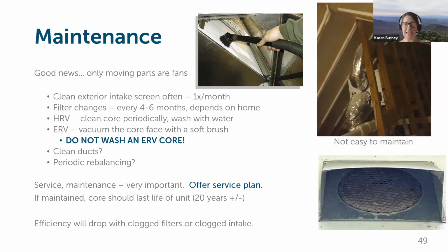And vacuumed, right? Last time you were saying that they should be vacuumed rather than just sweeping it off with your hand, which is what I typically do. Well, because if that's an intake and we blow it off or wipe it off, it's all going to get sucked right in by the machine into the house. But if you vacuum it off and pull it back out the way it went in, we're not going to do that. Generally, the exhaust ones are not as dirty because we're exhausting out of the house. We're not pulling in leaves and junk like that from the interior of the house.